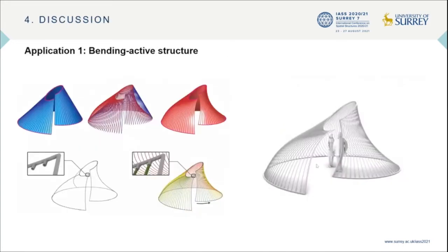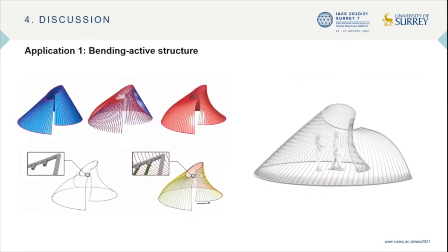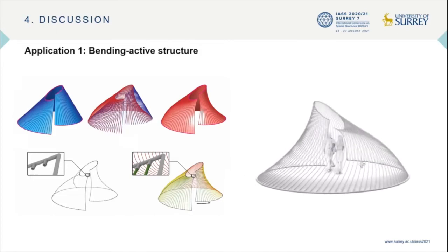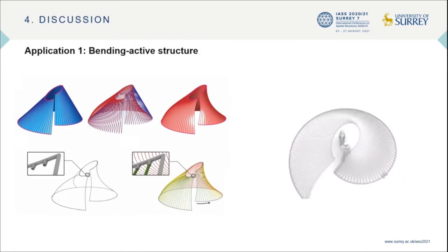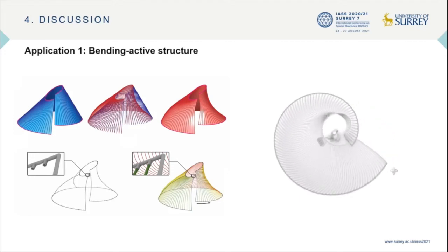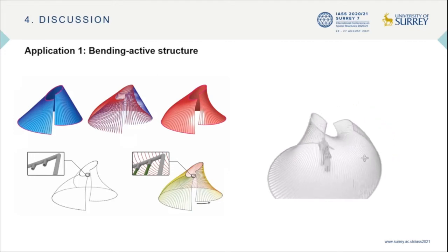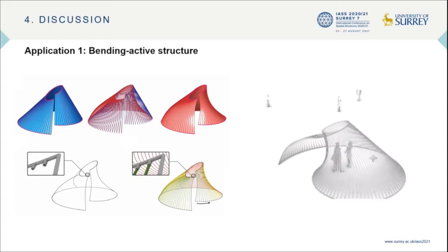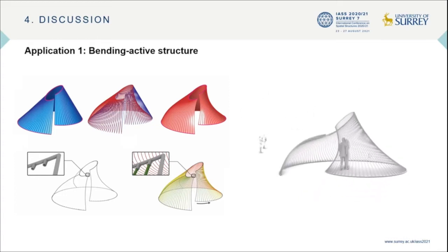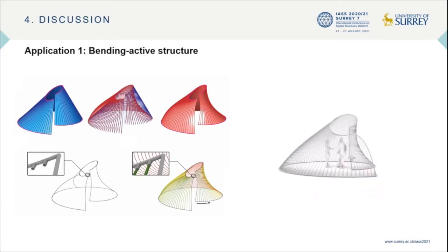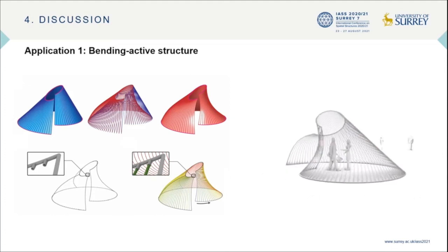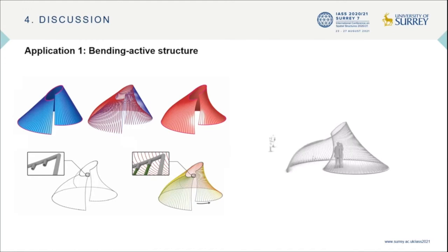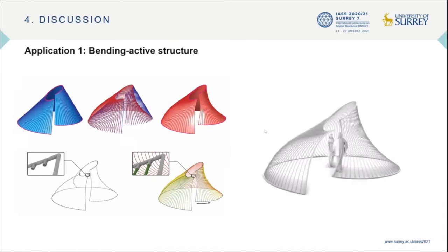Elastica curves are obtained from the fundamental theory of elastic bending mechanics, so elastica-ruled surfaces composed of elastica rulings can be adopted for practical applications that consider elastic bending behavior. For example, if we utilize elastica-ruled surfaces in the design of bending active structures, we can accurately capture the curve shape of the full system and avoid the need for numerical form finding processes.